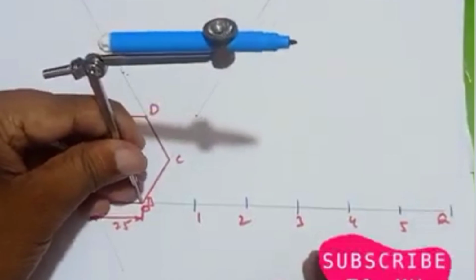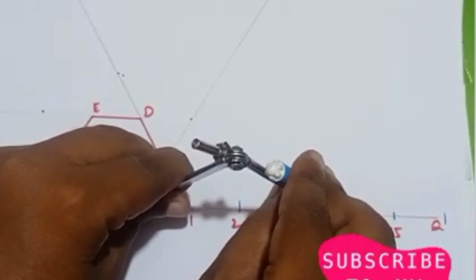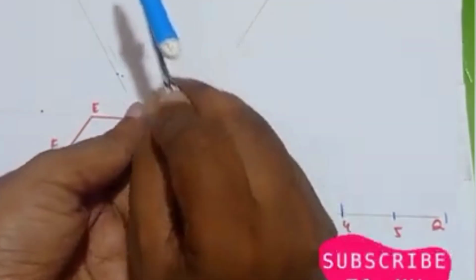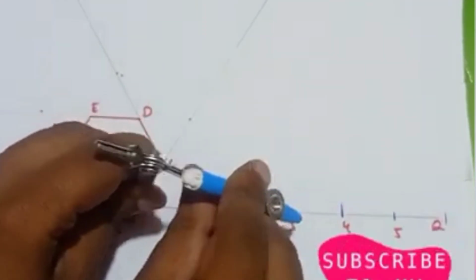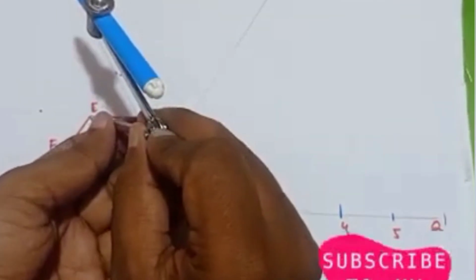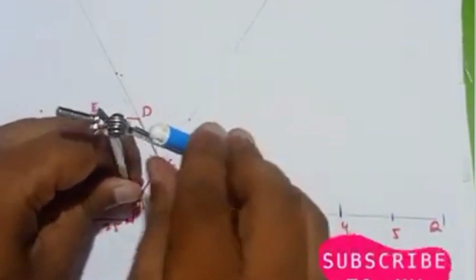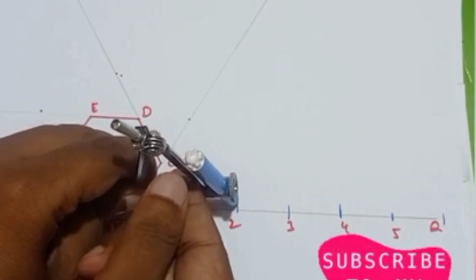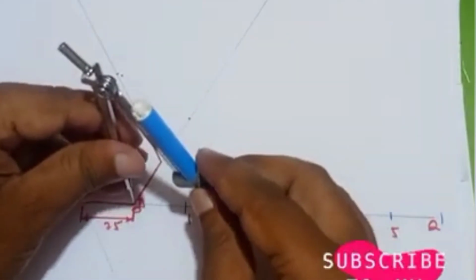Now again I'll be measuring from point P to 4. Keeping at the point D, I'll be cutting the arc. Same way, measuring from P to point number 3, keeping at the point E, cut the arc. Next from P to point number 2. And then from P to point number 1.